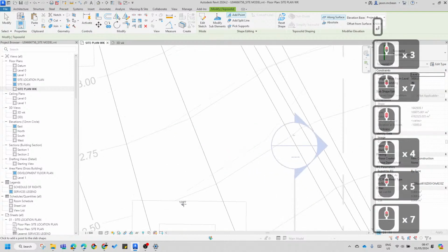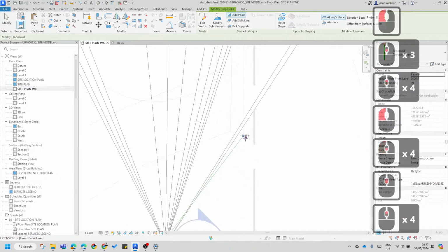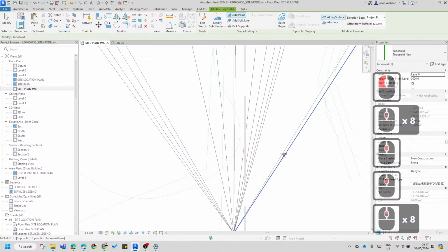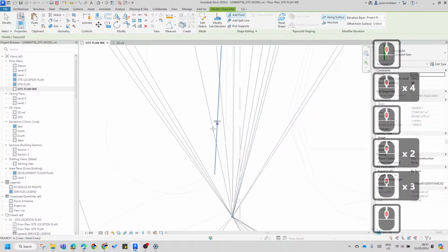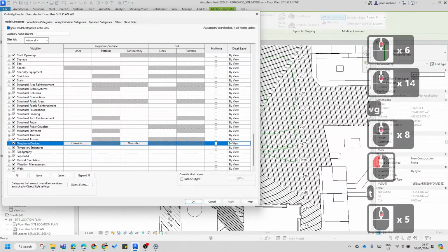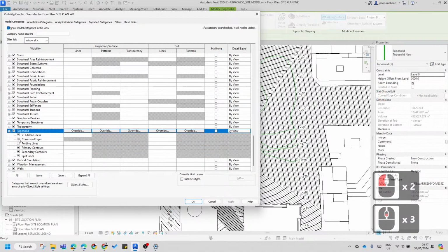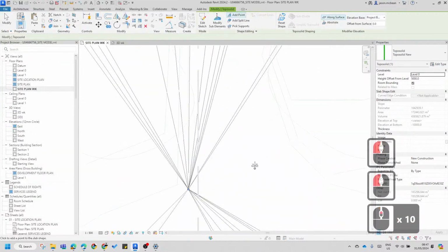Now you're going to add a point there. You're going to add a point. All it's doing is adding the triangulation. Oh my goodness, that's easy. No, it's not that bad. It's just if you lose the line work sometimes. I don't like this triangulation. So let me just go to VG and switch off the triangulation. So top is solid. Split lines we want. Okay, maybe in topography the triangulation is off. But anyway. Okay, so you're going to follow that.